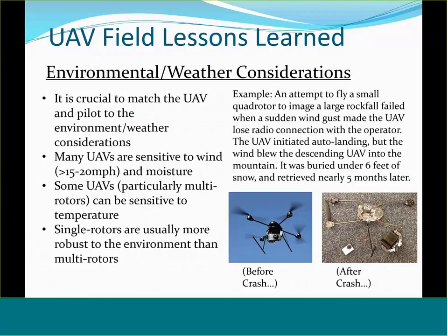I want to also focus on the importance of considering the environment that you're flying in as well as the weather conditions. It's very important to match the UAV and the pilot to the environment and the weather. Many of the UAVs that we've flown are very sensitive to wind, which means when you get a wind gust above about 20 miles per hour, it can knock them out of the sky. And so you need to be careful with that.